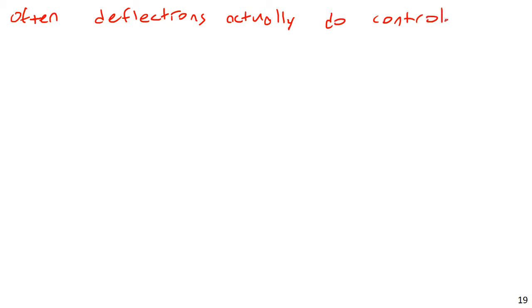Because even if you have a very reinforced member, it's very easy on longer spans to get deflections lower than those limits. So surprisingly, often deflections do control. So it may not seem like a big thing at first.